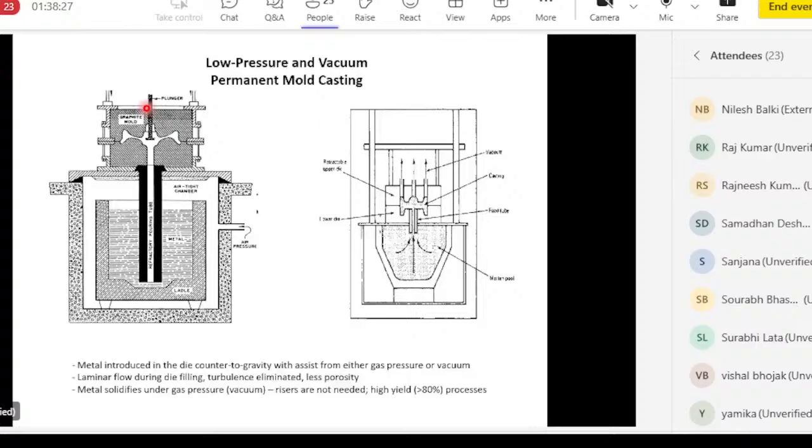A superalloy had flowed out and filled up this region here. And this aluminum crucible floated up and jammed against the bottom of this tube. Anyway, so this is how we use low pressure of gas to control the rate of filling.